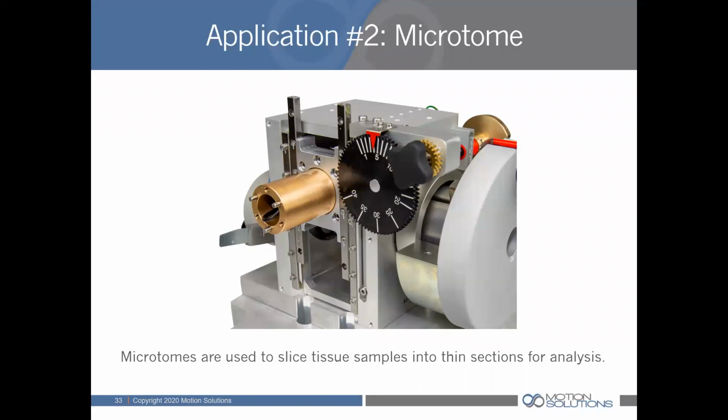So what we did is we put a very tightly controlled diameter brass shaft into a very tightly controlled bore. In this case, it's an aluminum housing with an anodized bore that's lapped very tightly to the diameter of the shaft. And so you still end up with virtually no clearance between the two and a very large surface area to support the load. That results in the maximum stiffness. And with that, we're able to cut samples that are very smooth and accurate. What we found is any clearance in the system will result in what they call Venetian blinds.